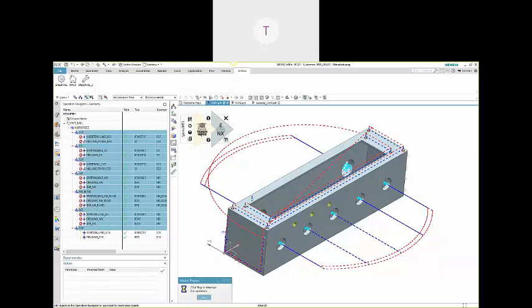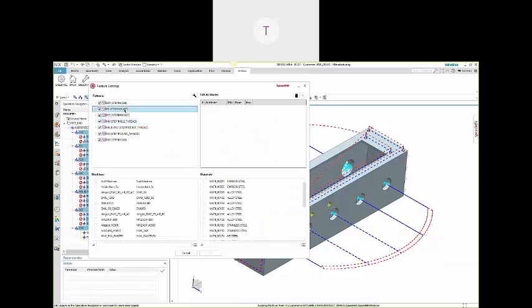So we're going to teach our operations now, and it's going to open up the Speedmill dialog box, and you can see here are the operations that we have taught. On the right-hand side, you can see the attributes associated with these operations. Now, of course, we have the ability to control additional attributes, including color, face name, PMI, and more. It just really depends on how we want to control our features. For example, some customers decide to make quarter 20 holes a certain red. So every time that red appears in the part, it'll know it's a quarter 20 hole and follow our best practices to make it happen in the programming process.